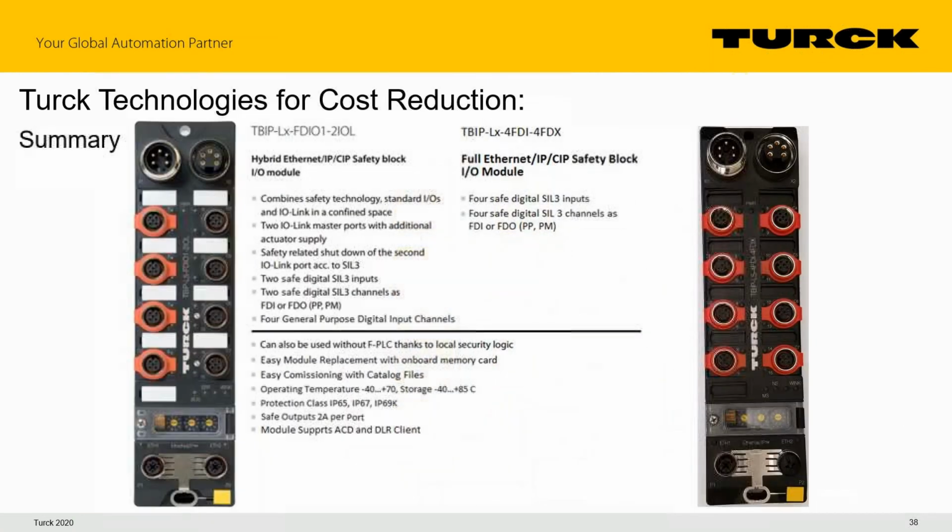So, why the use of remote safety? Well, there's a lot of I/O points to a safety device, whether it's a light curtain or an e-stop button. So by having the blocks out there close to the point, we're saving a bunch of wiring coming back. These blocks do have the ability to have that safe logic in them. So they can be used really in 3 use cases.